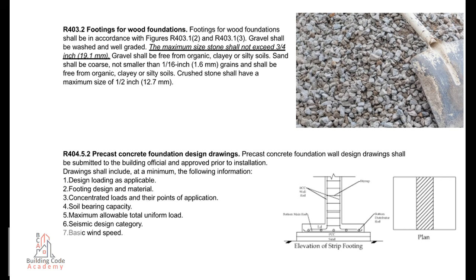R404.5.2 Precast concrete foundation design drawings. Precast concrete foundation wall design drawings shall be submitted to the building official and approved prior to installation. Drawings shall include, at a minimum, the following information. 1. Design loading as applicable. 2. Footing design and material. 3. Concentrated loads and their points of application. 4. Soil bearing capacity. 5. Maximum allowable total uniform load. 6. Seismic design category. 7. Basic wind speed.